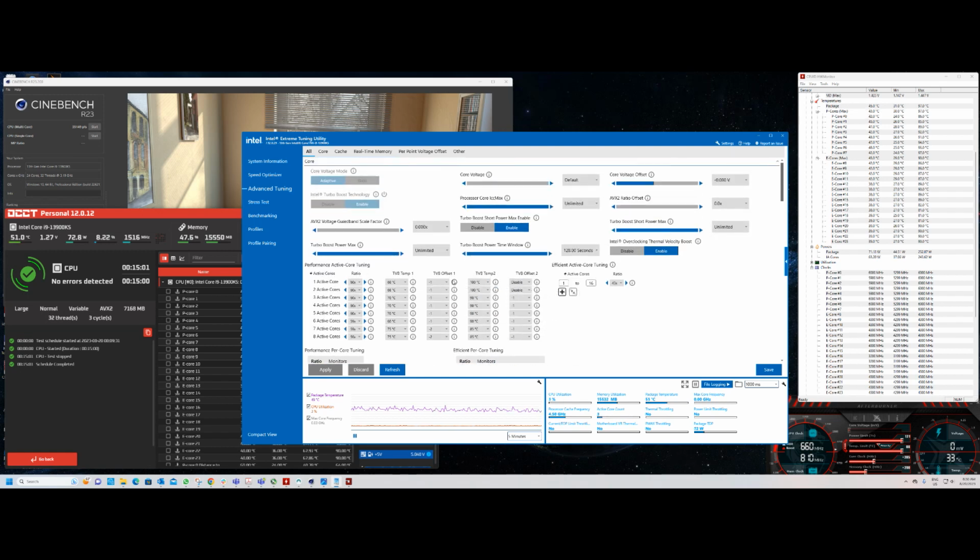And of course, there's more information, another panel, which I believe last year there was only one, but you can now customize the full potential of using TVB, which is also known as the Intel Overclocking Thermal Velocity Boost. When enabled, this process can, as it says here, reach the specific package ratio when below the specific temperature. If above the specific temperature, then the corresponding frequency ratio is reduced by the specific offset. So basically, it will normally run full speed.